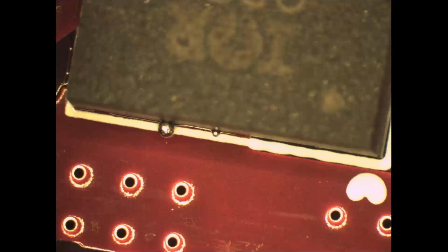Now, during the soldering operation, if you ever see on large packages solder balls to the edge of a package, like you see here in this example after reflow soldering, sometimes people refer to them as solder beads, like we see on chip resistors, chip capacitors, but this is more like a squeeze out defect. So if you've got solder paste reflowing underneath a package like this, we can get this phenomena where we get small balls coming out the sides.